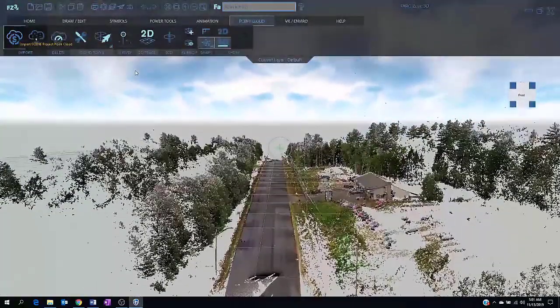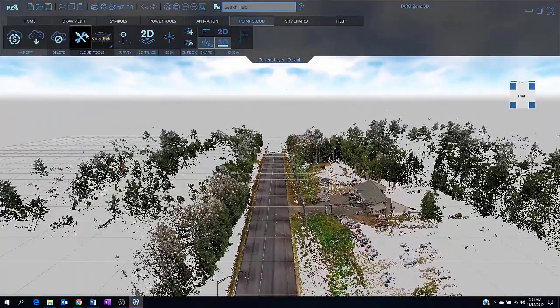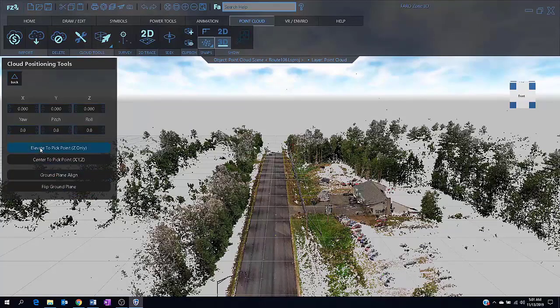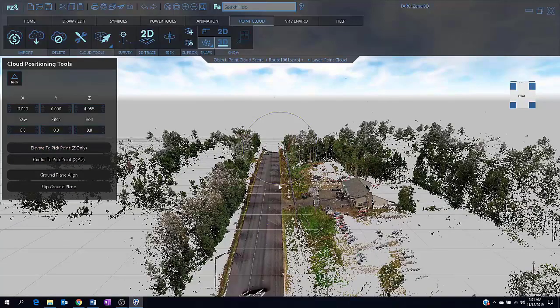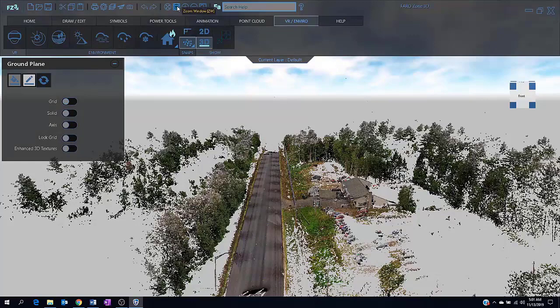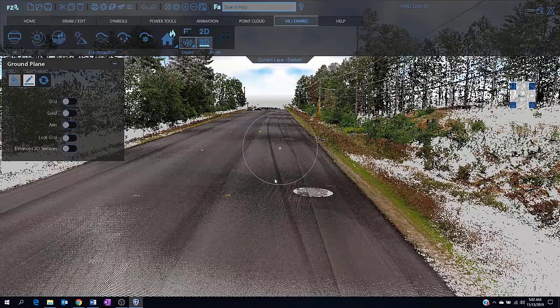Best practices. I had a step-by-step guide here, but I just wanted to explain to you what's occurring in the next two videos. We're at a place in the presentation, actually 10 minutes away from finishing, where I am in the first instance getting a speed analysis from the skid marks in that example I just showed you where they were very conspicuous. I'm using FARO Zone software to first import the point cloud into FARO Zone. Then I am marking the skid marks using the curve of the line tool. And then I am using the skid analysis button under the power tools tab to do the speed calculations, letting the software do the speed calculations. And then from that,